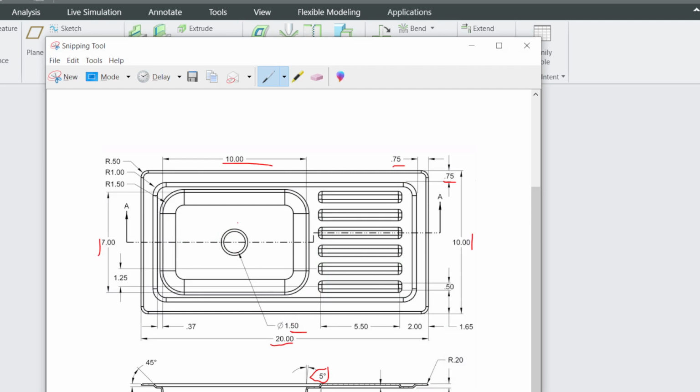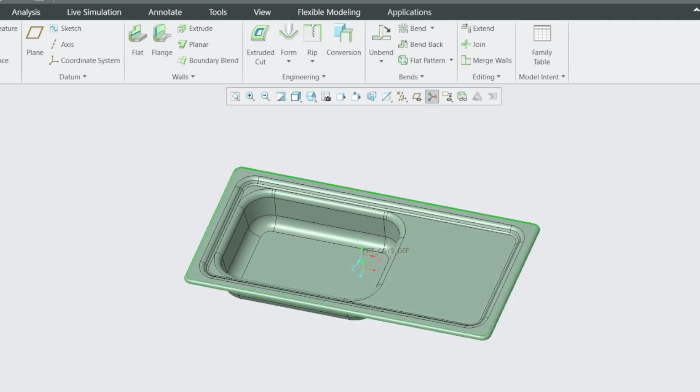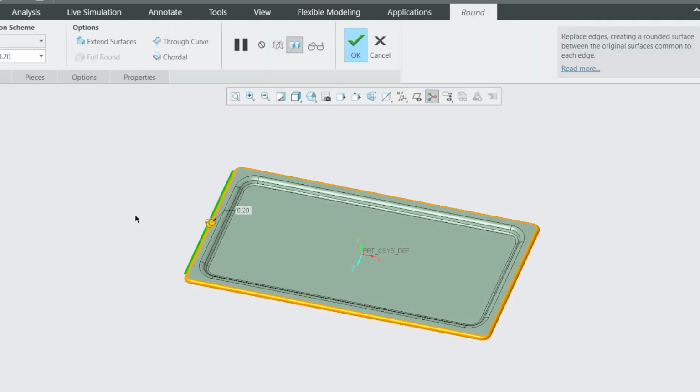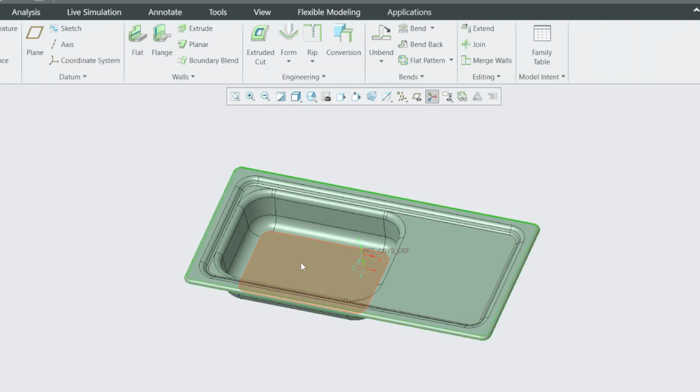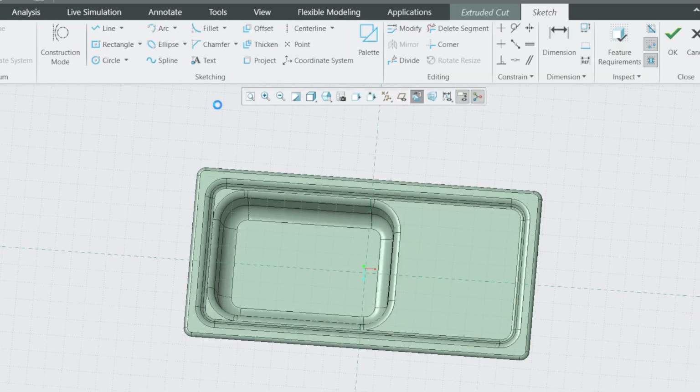The fillet is not defined, but we're going to use global fillet of 0.25, similar fillet we used here. This fillet we used here, this value, and we're going to use here. Therefore, we go to extrude cut this face normal.